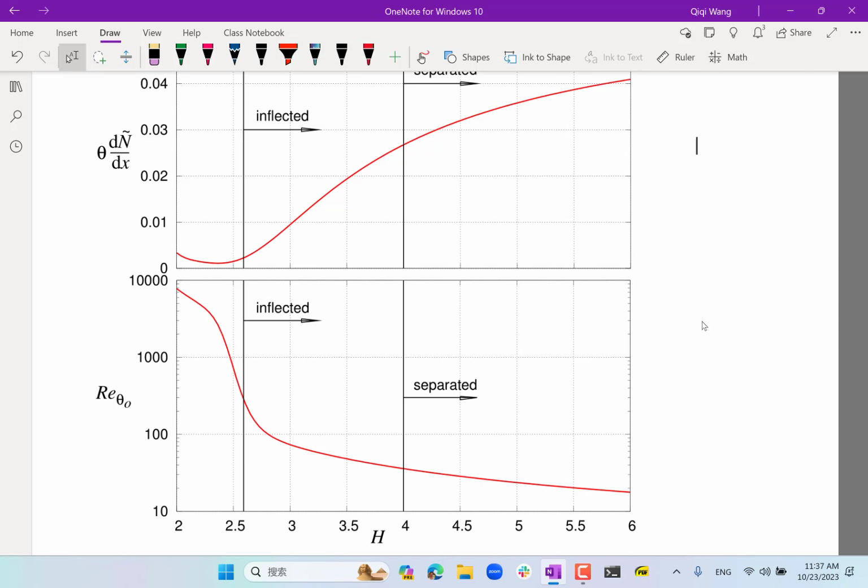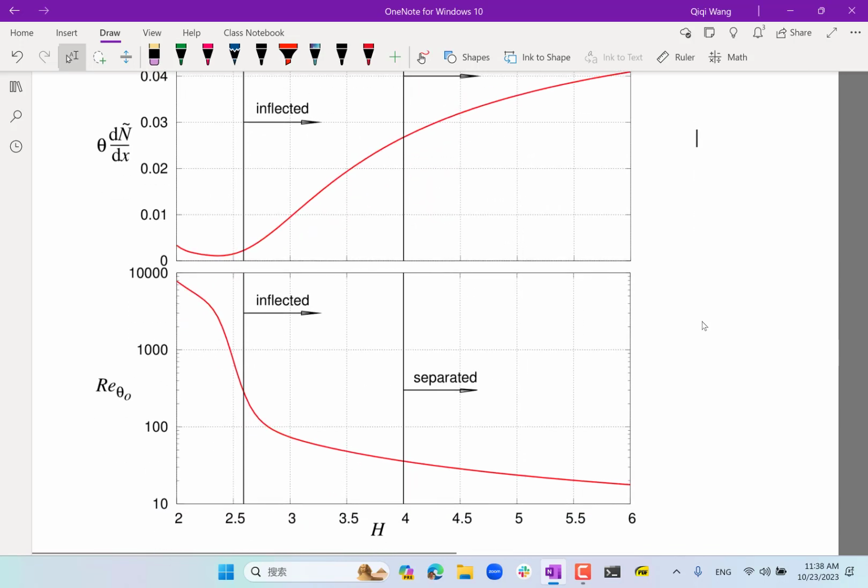Right, that's when the boundary layer becomes turbulent. And there are two difficult things. One is to predict how fast these instabilities would grow, but the even more difficult thing is to figure out how much of these small perturbations are there initially in the boundary layer, because these perturbations can be very small, right?